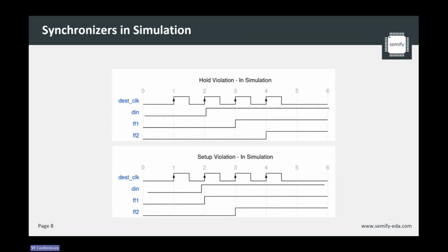In simulation, for the exact same cases, what will happen is that the simulator resolves the value at the delta cycle prior to the positive edge of the clock, or the triggering edge of the flip-flop. So there will always be this exact 2-cycle delay. So we need to bridge this gap somehow. We need to model this in some sort of way and take this into account.